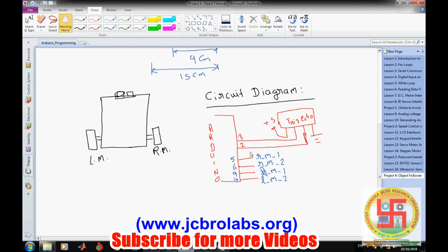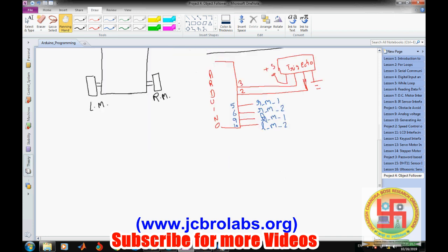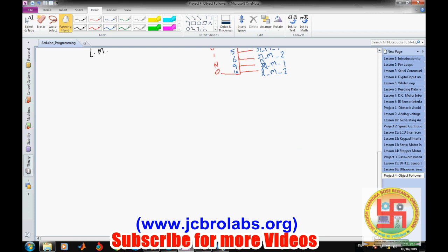Okay, so let's say your motors are turning too fast, so they have high RPM. You can use PWM to control the speed. If you are using PWM, otherwise you have to change the pins after writing the program. That's why we have used these 3 pins. Either you can use them as general purpose input output, or in order to vary the speed of the motors or the speed of this robot, you can use PWM as well, simultaneously. Okay, so now we will write a program.